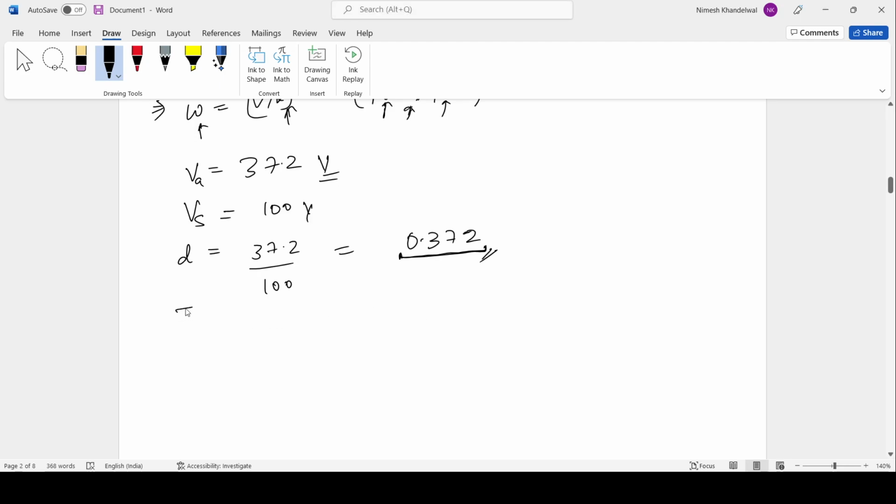And now the switching period. So what is this 37% of the time, in seconds that I'm talking about? For that, I need to first calculate the switching frequency, and the period is 1 over Fs. The time for which it is on is given by D times Ts.